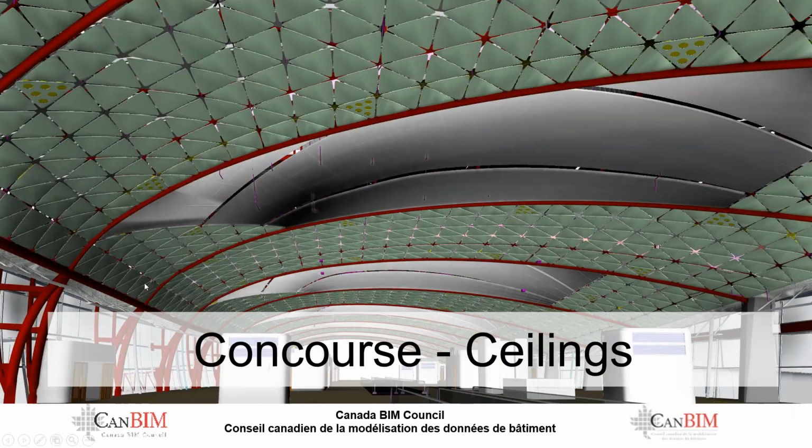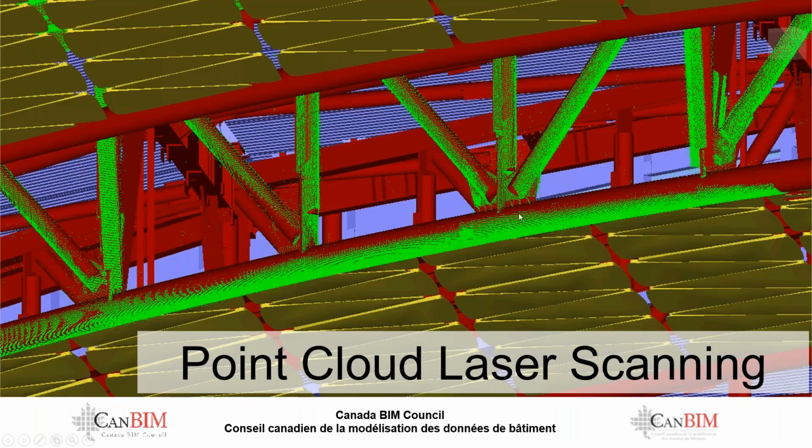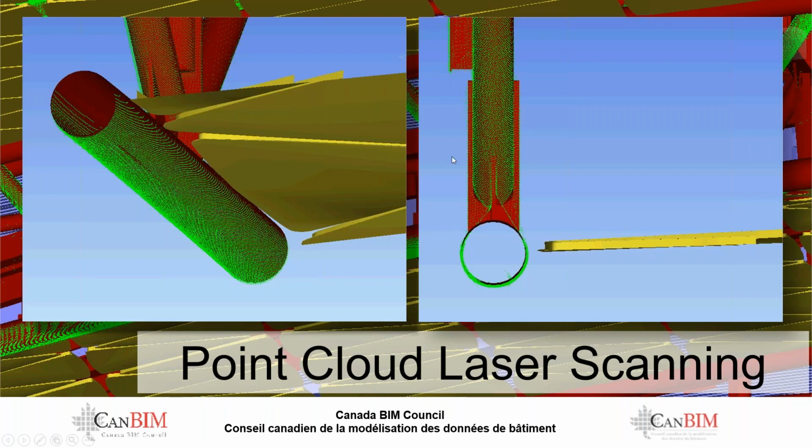So we actually scanned on site all the steelwork as it was erected. And you can see it here, this green blob. And we actually used the laser scan to compare to the actual fabrication models. So we were able to compare what was happening on site to what was actually designed and detailed. So we were able to tell if the chords for the trusses, which were in between the ceiling panels, were in tolerance and into specification.